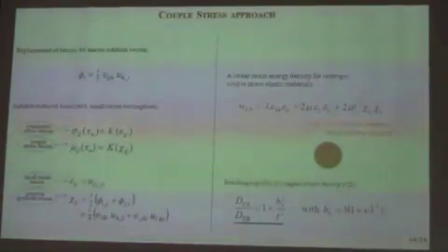By taking Euler-Bernoulli beam assumptions we can also derive the formulas for it and build the bending rigidity of the coupled stress theory in comparison to the Euler-Bernoulli theory, and we have the same structure as for the strain gradient approach, and only one material length scale parameter in a combination.